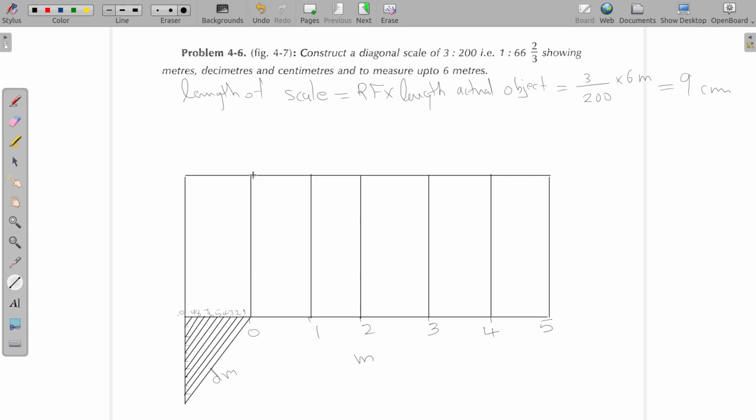Now what we do is that we also divide this part into 10 equal parts. If you have a mini drafter, it's easy for you, but since you don't have a mini drafter, you may have to do the same procedure here. Draw a line here, divide into 10 parts and connect parallel lines. That's what you need to do. But when you have a drafter, it's possible for you to mark these 10 points using these points, because it's easy to get the vertical direction in a mini drafter. So for the time being, I'm simply dividing this into 10 parts without using any special technique.